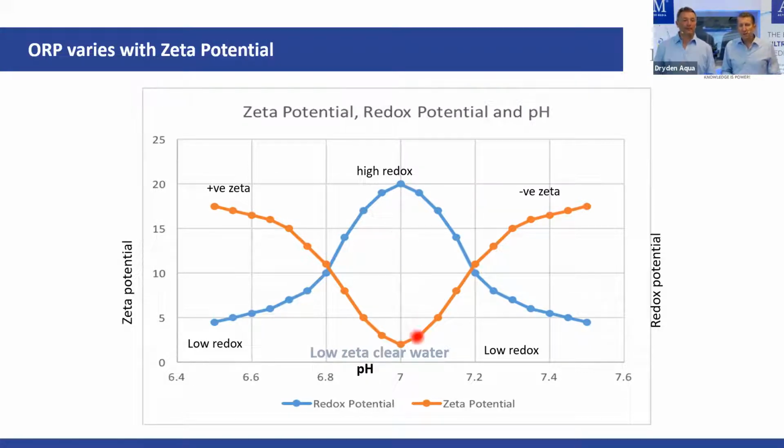If we have a neutral pH, that also means we have a neutral zeta potential, which means we have little charge between particles. We have big particles, and this is why the water is clear. The particles come together. Instead of having 1,000 small ones, you have maybe 10 big ones. Exactly, and that also means less turbidity. The water will become clear.